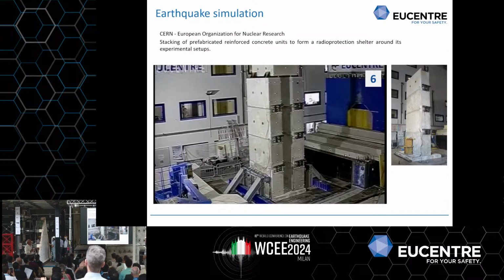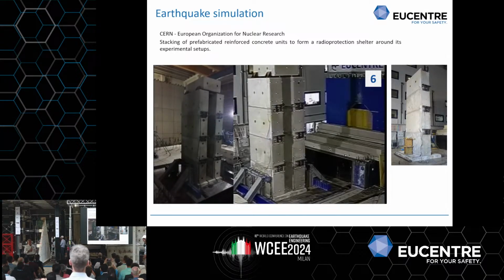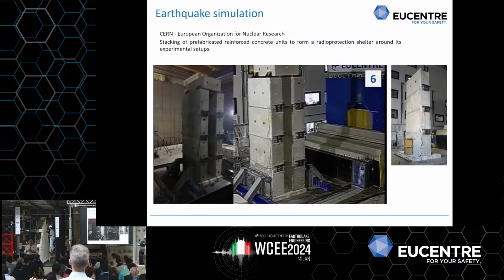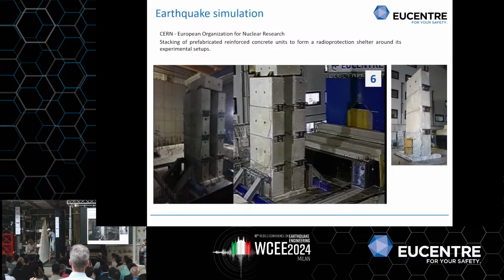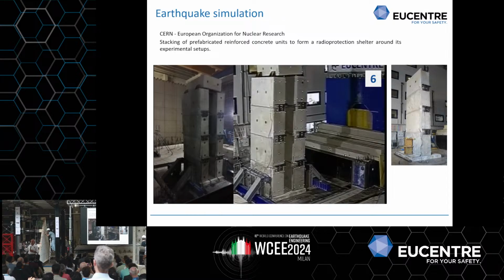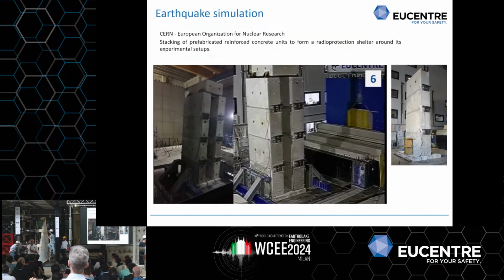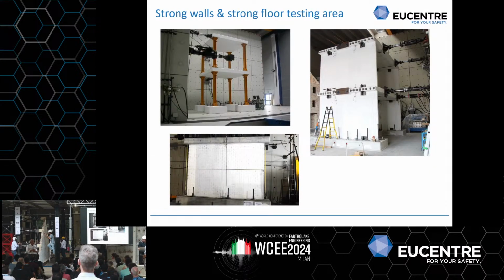On that shaking table we have been performing many tests on different structures, even up to 4 or 5 stories full scale. Now on the shake table in the other laboratory there is a masonry tower. I'm not sure, about 15 meters tall, something like that. Yeah, 14 meters tall, something like that. It has been already tested. It will be tested again this month. And the peculiarity of that case is that there is an active mass damper mounted on top to try to control the response of the tower.